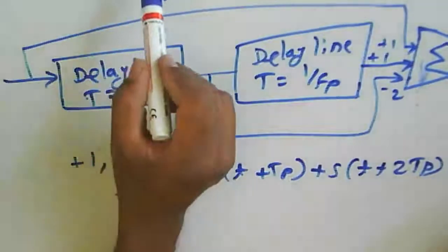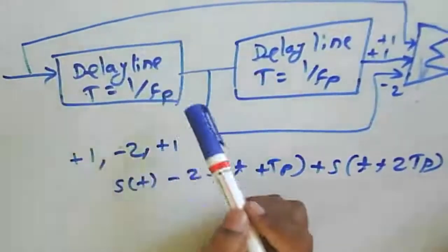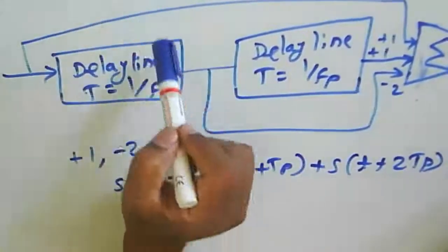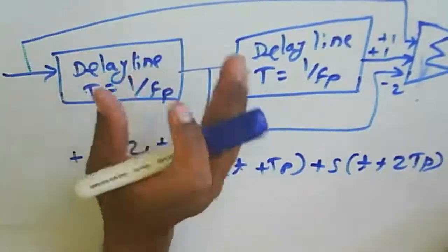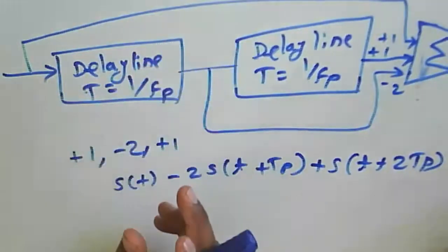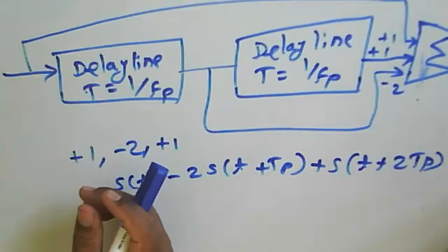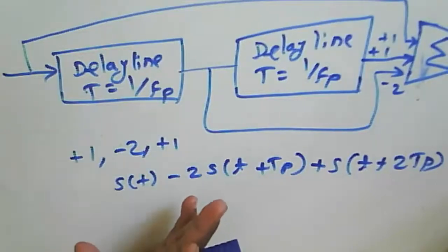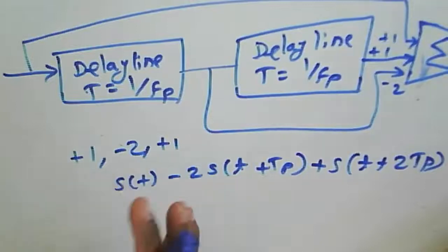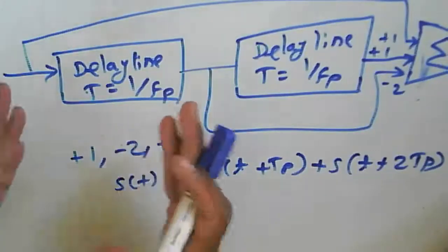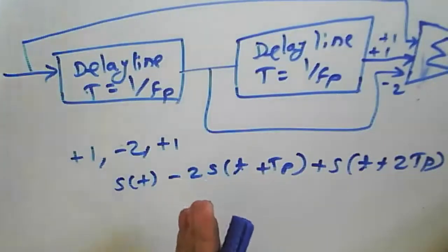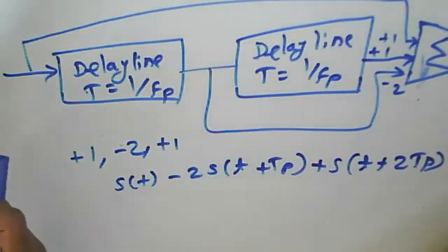So this two delay line canceller and this three pulse canceller are both the same now. If we consider an nth pulse canceller, the frequency response of that particular nth pulse canceller is the same as the n single delay line cancellers in cascade. So the larger the number of delay line cancellers or pulse cancellers we are using, the larger the attenuation will be.